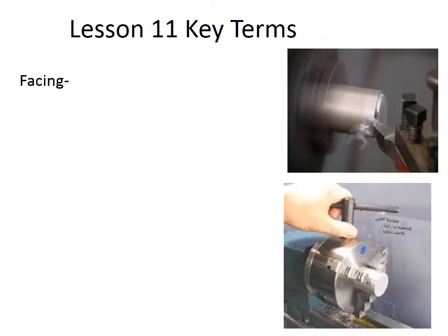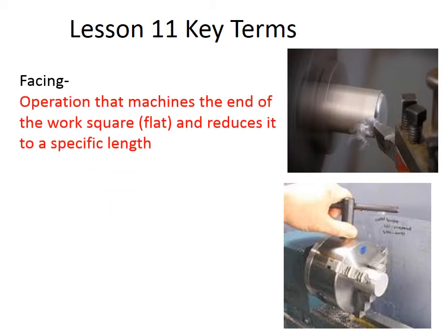On your screwdriver handle that you will make, you're going to do something called facing. You're going to have to face both sides. This is a picture of a lathe with a piece of aluminum stock inserted, and all they're doing is cutting the end off. They're going to make the end really nice and flat and smooth. You will do, again, both sides of your screwdriver handle. You want to make both sides really flat. As this is spinning, your cutting tool is just going to go straight across, and it's going to perform your cuts.